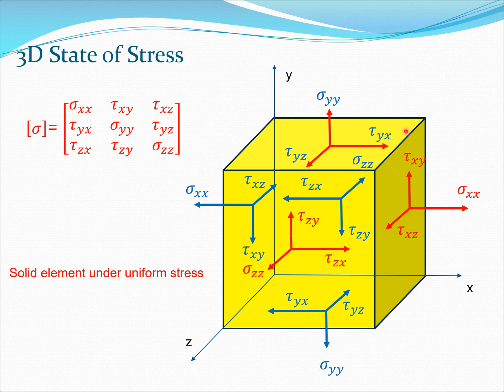Again, remember what I discussed at that point is that the way you get the shear stresses is that you take the plane where they act. For example, in this case they are going to act in the x is constant plane, so that gives us the tau x and tau x here. And the second part comes from the directionality. So this is acting in the z direction, this is acting in the y direction. So that's how we get tau xy and tau xz. And these are in the positive facing sides, or the side facing toward you, which I have made in red. The other sides act in the reverse direction because you need to have equilibrium in this particular condition.